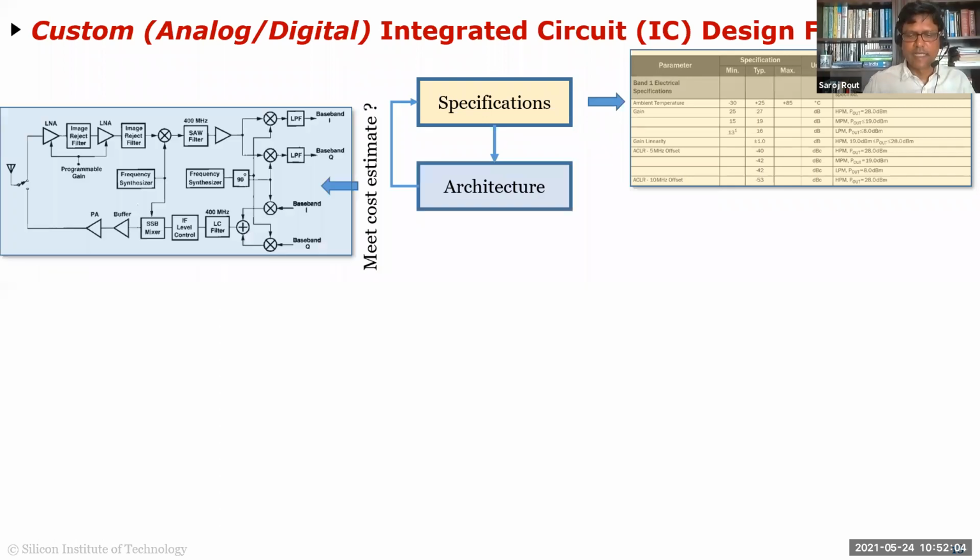Okay. So as designers, if it's a simple chip, it's usually one designer or two designers or three designers. They're the ones who are architecting. So they will come up with some architecture, and the architecture is a place where it is mostly technology independent, but in analog, pretty much everything is technology dependent. You have to choose a certain technology, like you'll say, okay, I want to go with 130 nanometer TSMC or a 350 nanometer IBM process or something, because it's so tied together. And I'll show you in digital, they don't care about a technology till they get to synthesis. But in analog, they're so tied together that typically in architecture, you come up with an architecture where it is technologically independent.